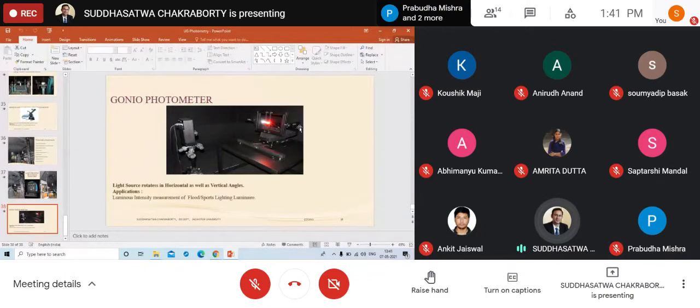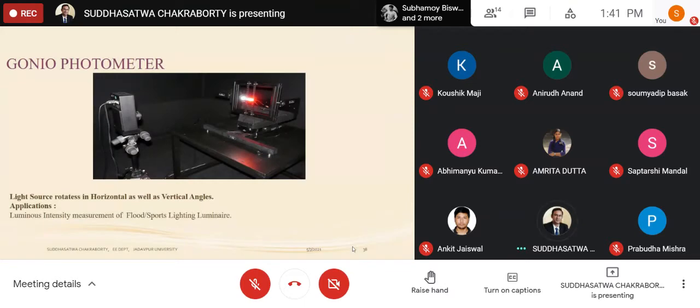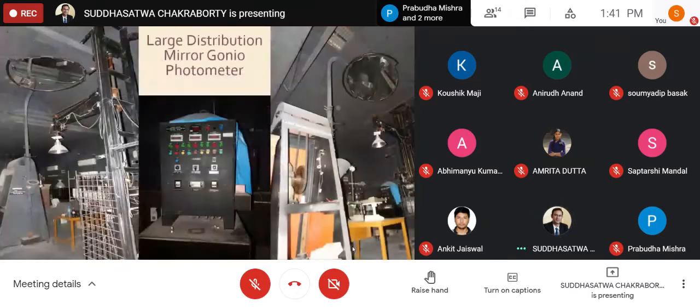The modern goniophotometers are fully automatic, as I was telling you, for LED photometers, because here both the C and gamma intervals have to be made as small as possible. So it should have very fine resolution. Photometric measurements also comply with the 4 characteristics which are essential for any measurement: number 1, accuracy; number 2, precision; number 3, resolution; number 4, sensitivity. When we talk about any measuring instrument, I think you have already gone through this in your second year measurement classes.